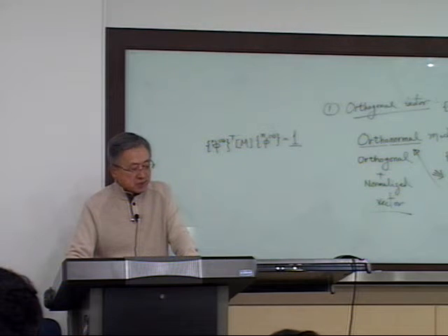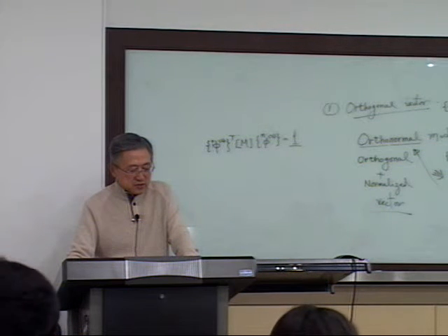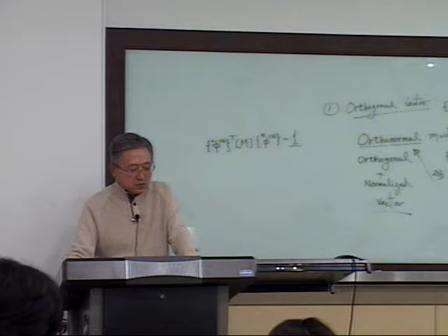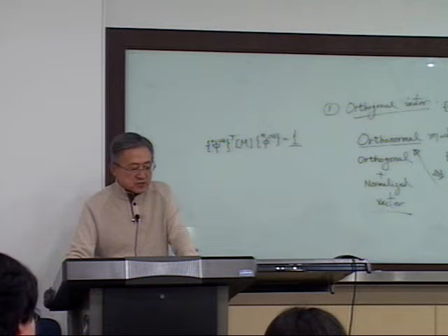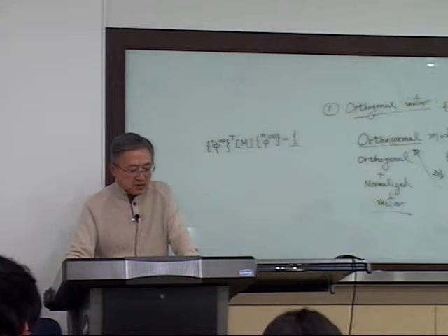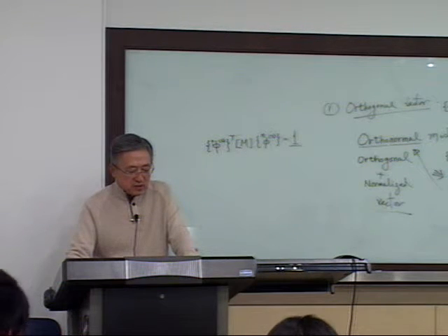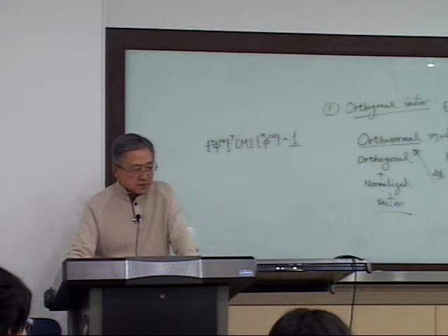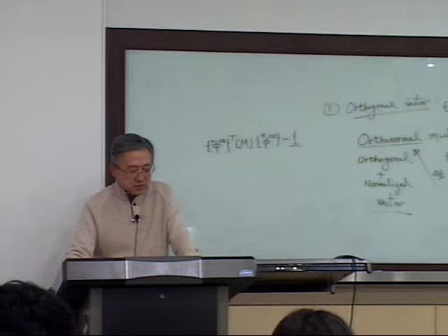This is a time domain function because small v j is a time domain function. If you take a sum of all the modes, it should be equal to the sum of all the physical forces. Then F i j from here, i is the degree of freedom, j is the mode. You have that expression. Over here it is still a function of t because v j is a function of t.